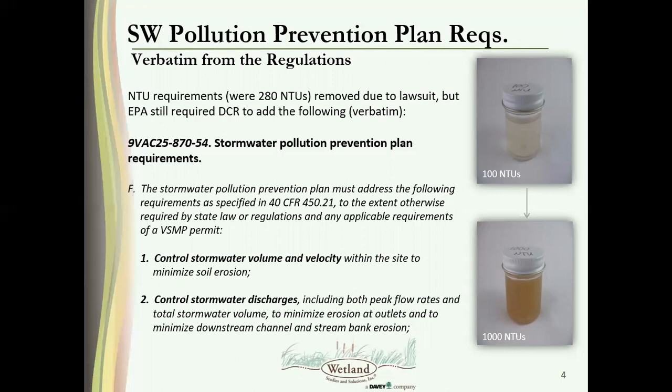And it's a really fancy way of measuring how cloudy the water is. The way it's actually measured in a lab is you take your water sample and you shine a beam of light through it, and it's basically how much of the light you're shining through the water comes out on the other side. So if you've got pretty clear water, then you're going to have a low NTU number. If you've got pretty turbid water, you're going to have pretty high NTUs.